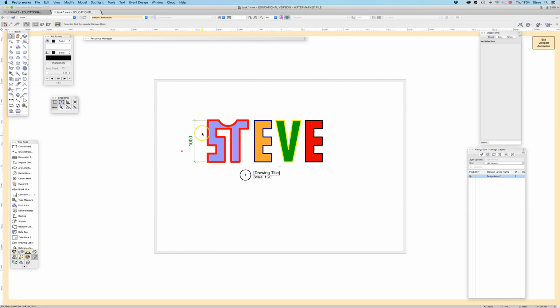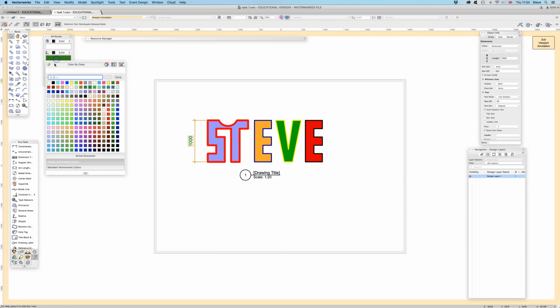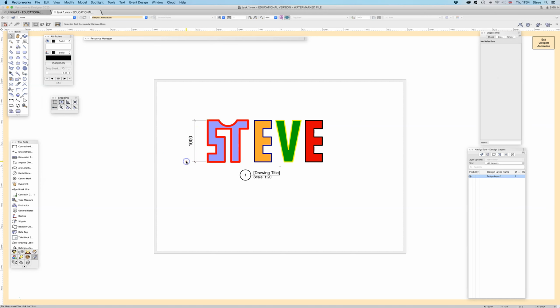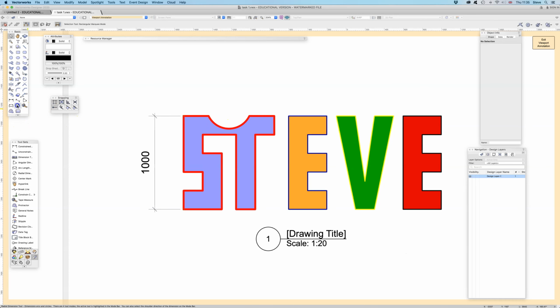I wouldn't recommend it because there's absolutely no reason to do that, but just saying that it's editable like everything else. So I can give some of these dimensions. I can give the arc here a radial dimension, because again, if we were wanting to build this, that's probably a useful thing for carpenters or anybody else, somebody cutting out material, to know what that radius is.